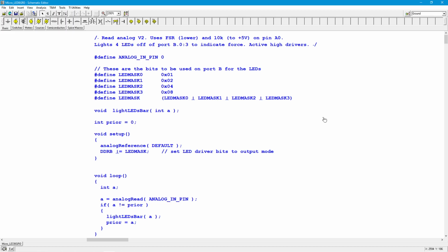Now, if you wanted to use higher resolution, in other words, you want 12 segments or 16 segments or something, then you'd have to get a couple of ports and write to those, all right? No biggie. A couple of minor things with formatting here. For some odd reason, Tina TI did not like the single vertical bar character that we would use for a bitwise OR.